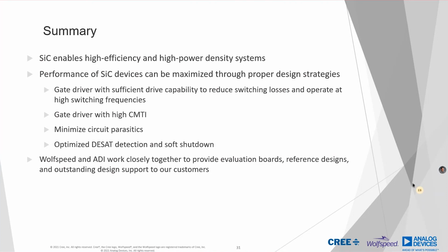And so it's important to select a gate driver that has sufficient drive capability to take advantage of those switching frequencies and bring the losses down. But it also has to have proper immunity to those common mode transients. And then, focusing on the layout, really dialing in a design to be tuned for silicon carbide, minimizing parasitics and things like that, will really help highlight the benefit of the high switching speeds.